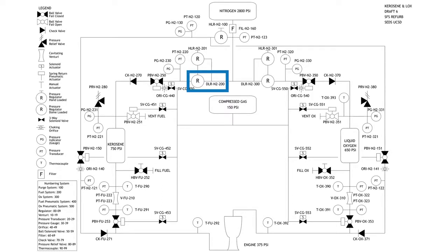So what's happening is that this nitrogen bottle at 2,800 psi is going to let nitrogen through that dome load at 2,800 psi. That's a lot of pressure, but these dome loads can handle about 5,600. It's going to take 2,800, it has a memory for 750, so out of the side of the regulator, it's going to let 750 out. We're going to regulate it down from 2,800 to 750. That's what that regulator does. Any questions on dome load versus hand loads?